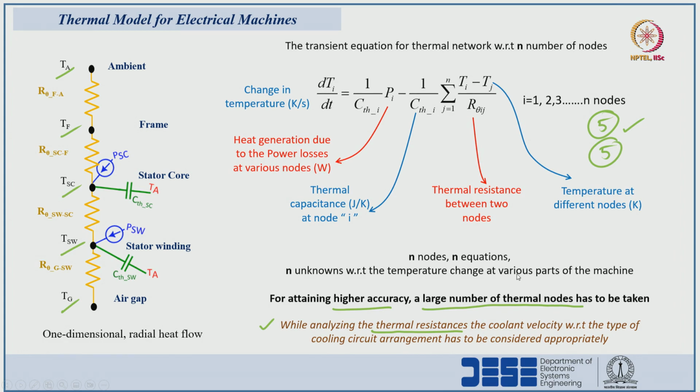While discussing the thermal resistance with respect to convection and radiation, I have mentioned the convective coefficient in the form of velocity, and the radiative coefficient we have to take from the table. So, Hc, the convective thermal coefficient, we have to calculate based upon the coolant velocity.